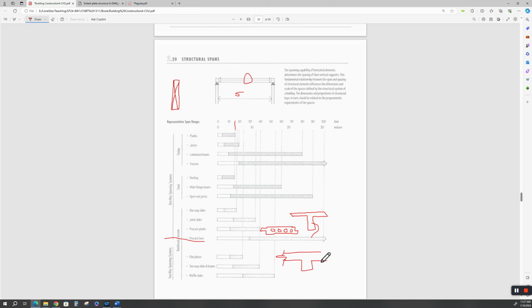Here's the upper part of this concrete slab. And then here would be your beam. There's your stirrups for your reinforcing steel. These are very expensive to form up. Your forming cost for concrete is your most expensive cost.